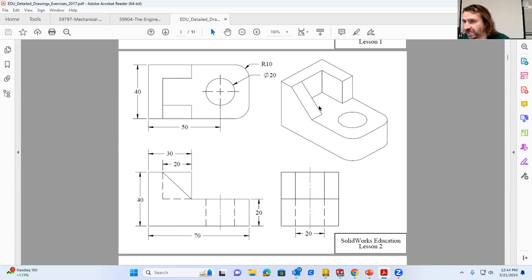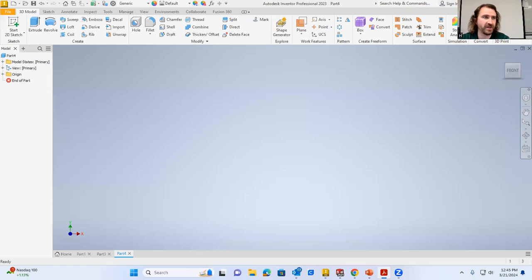Plus this empty space that is here between these 2 walls of material, I could draw this in, but if I extruded it, it'd be solid material. I have to cut that out again. I'd have to cut this out and this circle out. So the fastest way is to actually draw this top view and extrude these profiles and leave this circle profile unextruded. And so that's what we're going to do. I'm going to work on it that direction as my starting point.